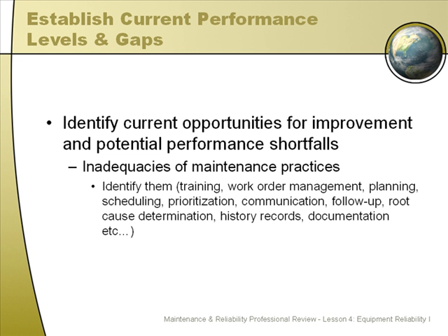In particular, follow-up, root cause determination, history records, and documentation can sometimes fall on the back burner as breakdowns control everything in a reactive maintenance operation. If you don't have people that are dedicated to doing good follow-up and analysis and root cause failure determination, and someone who's documenting their work, and actually all the maintenance people should be experts at doing documentation, then your history records are going to suffer, and you're not really going to be able to eliminate failures permanently.